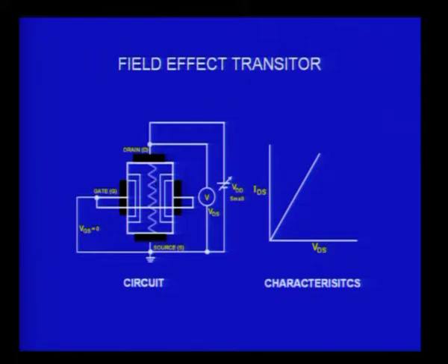It has got some value very close to the top, it has got a higher value because the voltage there is more, and as I come down there is a drop along the channel because the channel is something like a resistor, and therefore at different points along the channel the voltage is different, less and less, and therefore the reverse bias between the gate and the channel is also different at different points. It is maximum at the top and minimum at the bottom. What is the effect of this?